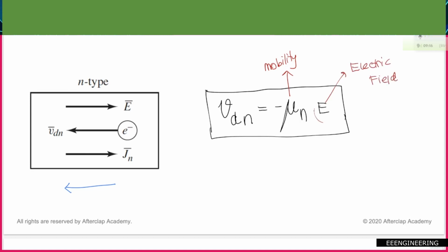So here's the thing. For low doped silicon, the value of mobility is around 1350 centimeters squared over volt seconds. And mobility can be considered as a parameter that shows how well an electron can move in a semiconductor. So you can basically think of that one as a unique feature of an electron. So that's the mobility value.